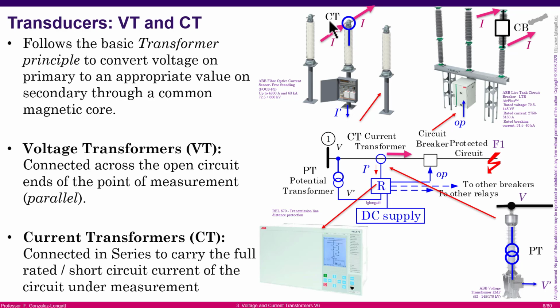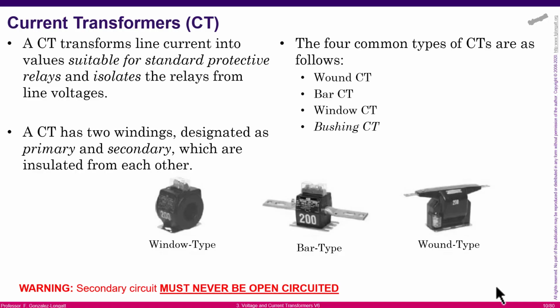And on the other hand, we can identify in that figure the potential transformer, called in some countries potential transformer or voltage transformer, but you must realize that the voltage transformer is taking signals or measurements between the line and what is the neutral or ground point, okay? Well, but let's jump into more details about current transformers.